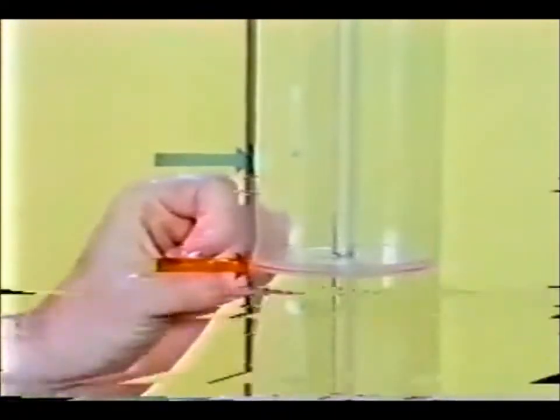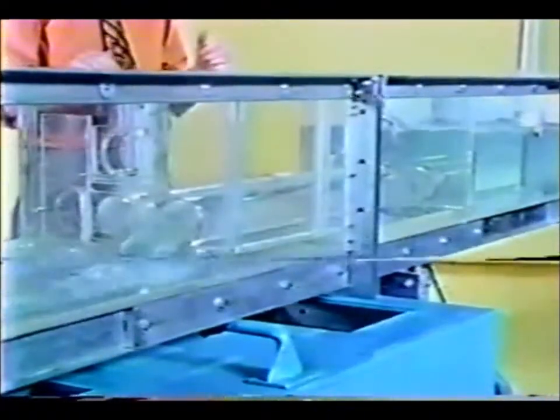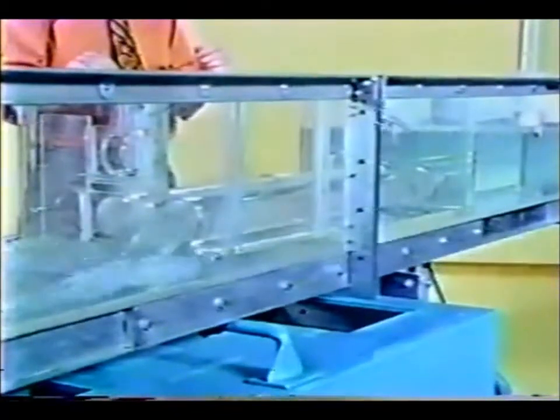As you might expect, the headwater elevation drops. This illustrates that to accommodate the same discharge, a smooth pipe requires less energy than a rough pipe. Another factor that influences culvert design is tailwater elevation.